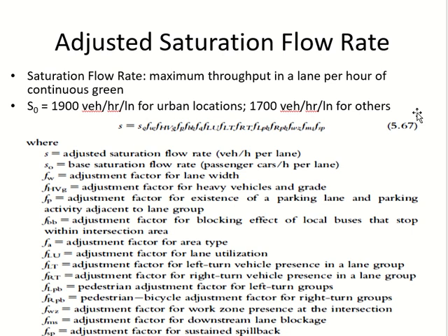This is the base value of saturation flow rate. Then you apply adjustments to the base value to calculate the adjusted saturation flow rate. So the base value comes from where? From the inverse of the headway. Then on that base value, you will apply these adjustments.